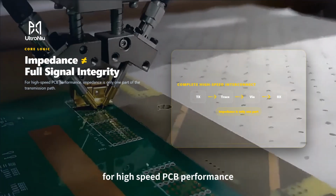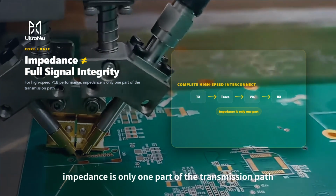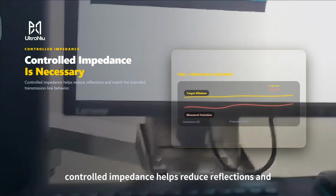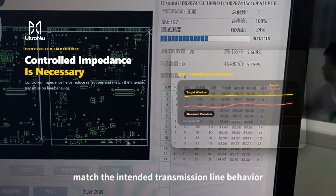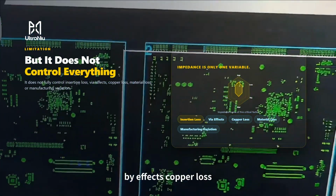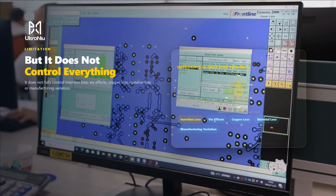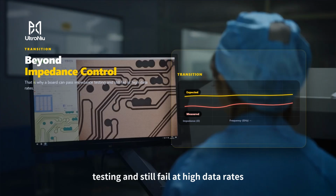For high-speed PCB performance, impedance is only one part of the transmission path. Controlled impedance helps reduce reflections and match the intended transmission line behavior. But it does not fully control insertion loss, which is affected by copper loss, material loss, or manufacturing variation. That is why a board can pass impedance testing and still fail at high data rates.